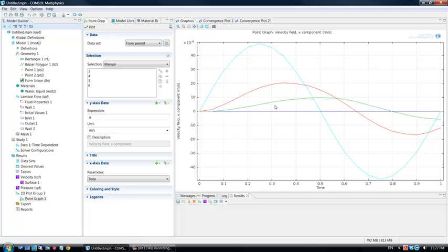And when it's 1 millimeter away from the top plate, the amplitude is even less. And when you're at the other end, at 2 millimeters away, the amplitude is 0. So you see that the amplitude is decaying as a function of distance, which is your viscous penetration length. That shows it to you very nicely as well.